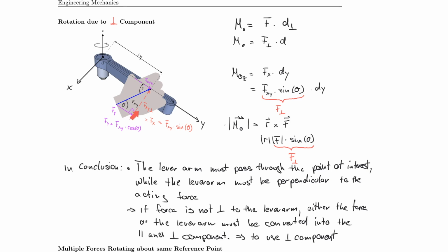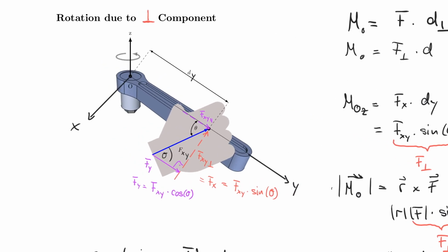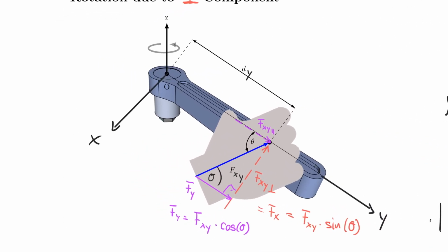And again, in this case, I used the perpendicular component of the force, but I also could have kept the force in its original form and then just turned the lever arm into its perpendicular component. Just for completeness, let me zoom in on that one and show you how that would look. So I could have, for example, found a point where I end up with a right angle here, and then I would call this R, and I could also find the force times that distance.